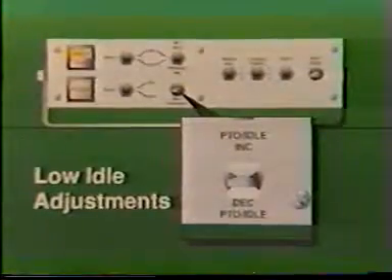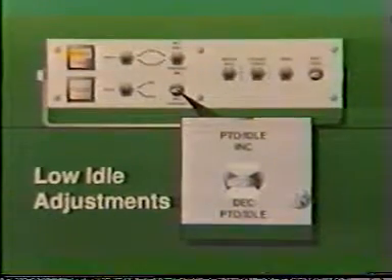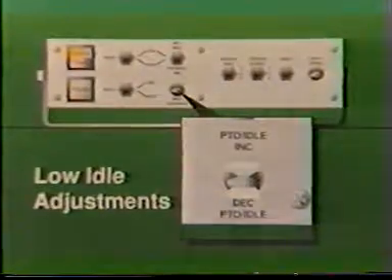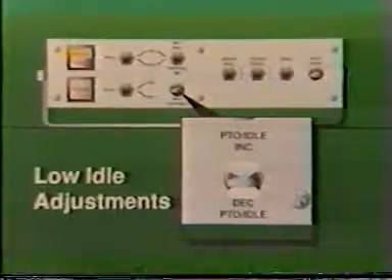The low idle speed setting is set by calibration. It can, however, be modified by the increment-decrement switch. The speed can be increased or decreased by toggling the increment-decrement switch.